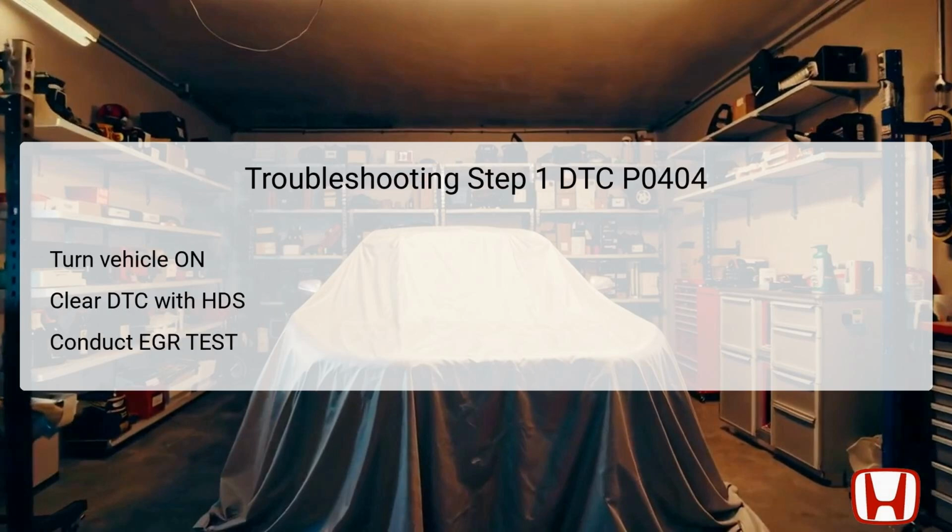The first step in troubleshooting the DTC P0404 involves verifying the existence of the problem. Begin by turning the vehicle to the on mode without starting the engine, allowing electronic systems to activate. Using the Honda Diagnostic System, HDS, clear any existing DTCs. After clearing, start the engine and hold the engine speed at 3,000 RPM without load until the radiator fan activates. Then let the engine idle to observe the performance. Conduct the EGR test using the HDS to evaluate the functionality of the EGR system.